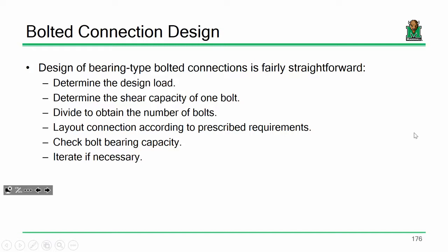Now they're pretty straightforward. Bolt shear, we're talking about the bolt shearing in half or snapping in half, and for the plate, we're talking about the plate failing, either the hole stretching out a little bit, bolt hole ovalization, or the plate literally being torn out. So we have bolt tear out and bolt hole ovalization.